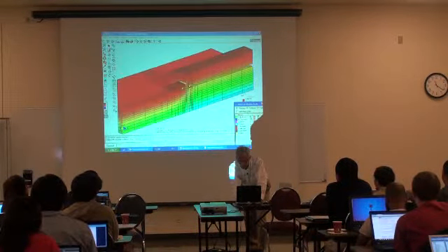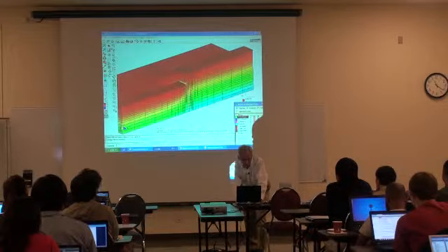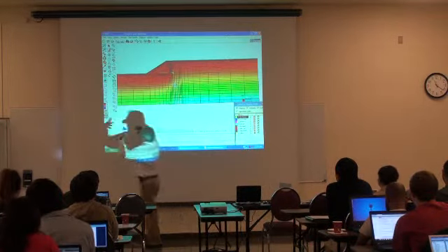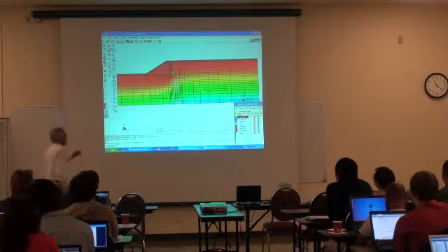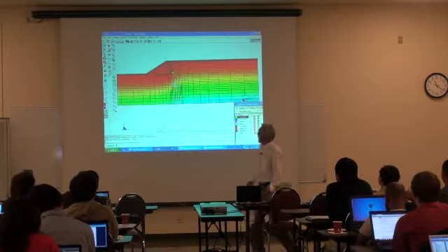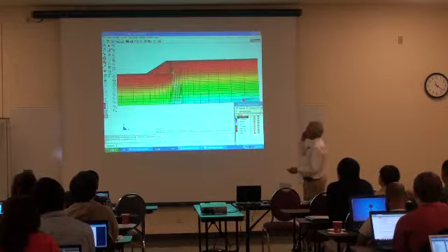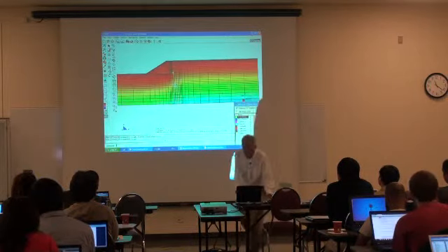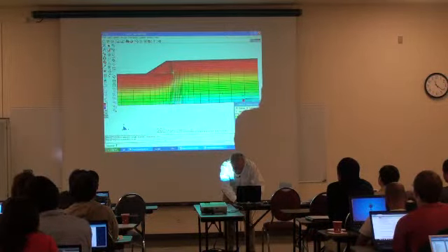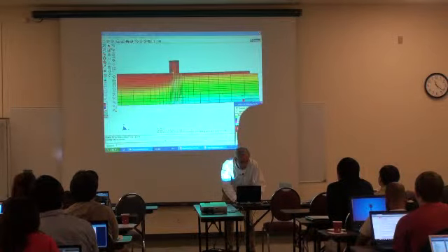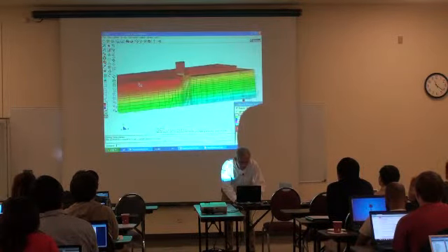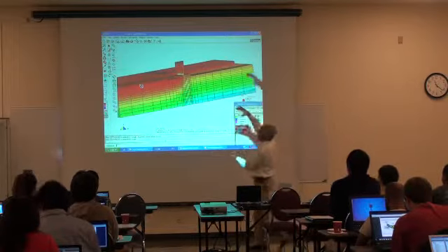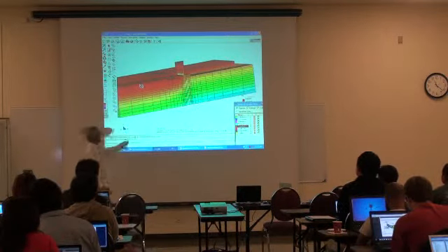These are all the elements. You see the distribution of vertical stresses due to gravity. That's the type of thing that we look at, and we start looking at problems. What is happening here? Why do you have the stress concentration? Well, what you have here is an abutment and the footing. If I remove the embankment, you will see the structure. Due to gravity, there are some slight movements, and this thing is under stress.